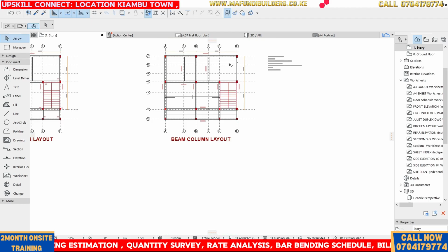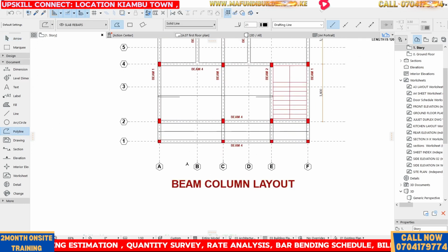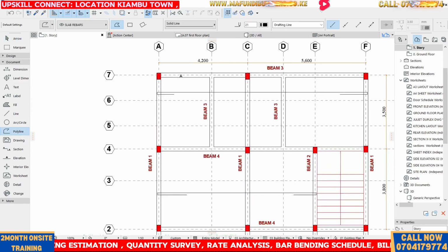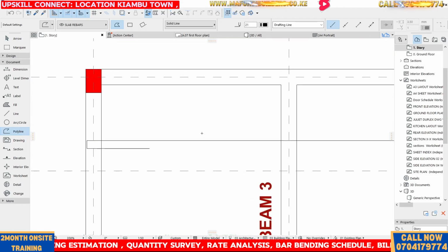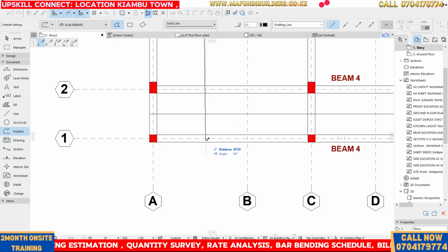How are you going to put the B1, the B2? This was B1, so let's do the B2 now. I'm going to take a bar, and one of my bars is going to start from this side. It's going to have this return bar because this is a free continuous edge. Then put 100. Then bring this all the way like that.